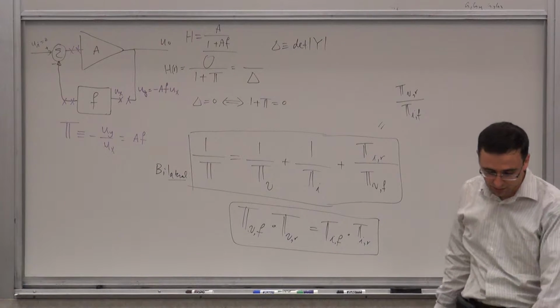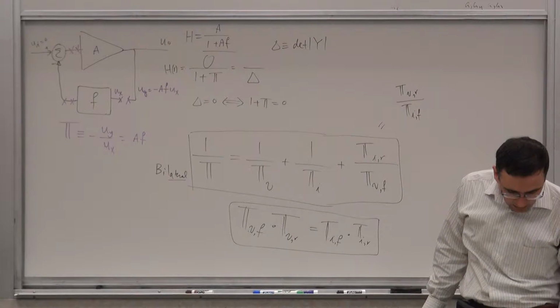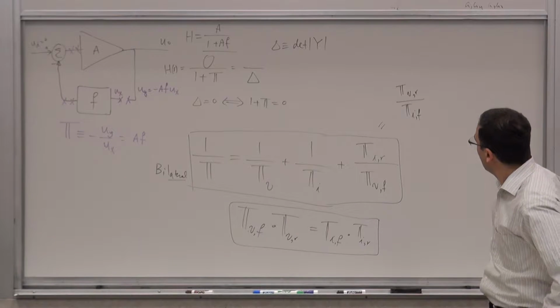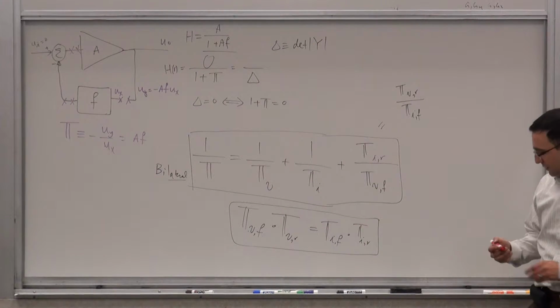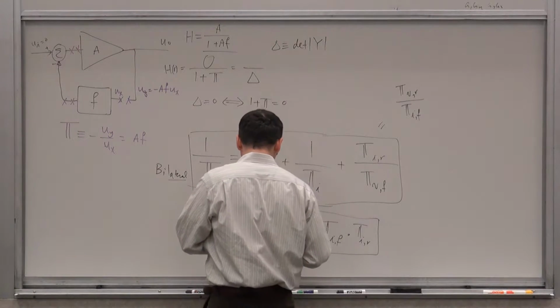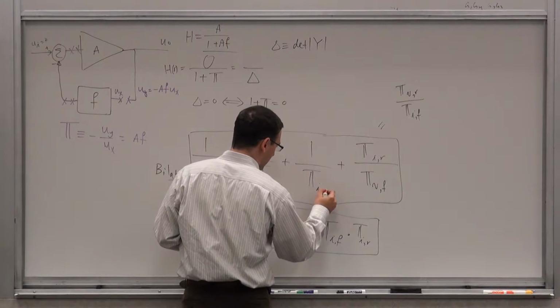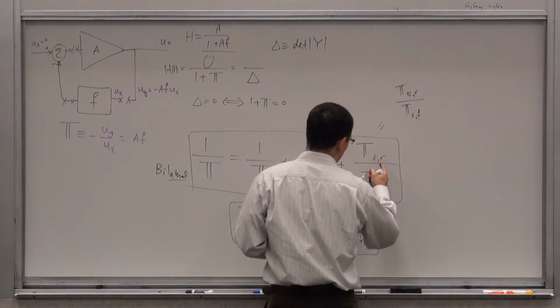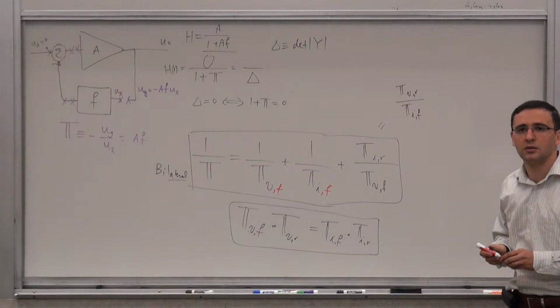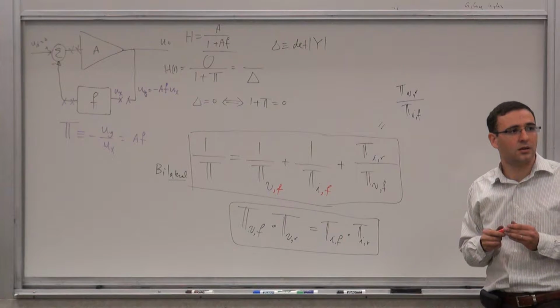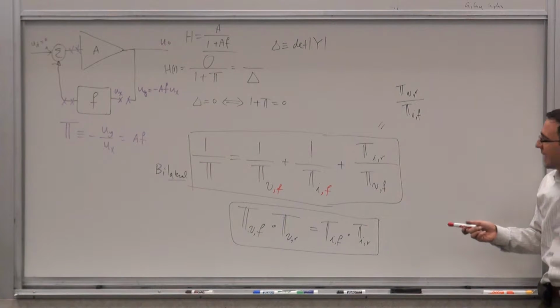So there's a correction term. So what you need to do is to calculate one of the reverse loop gains and the two forward loop gains. So this would be Tv forward, Ti forward. And this would be Tv forward, and this is I reverse, or V reverse divided by I forward. So, makes sense again in this term too.